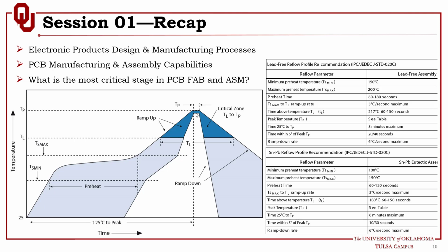So there is no specific or generic profile for all boards. No, there are several factors that govern the profile you are using for soldering. The factors are the maximum or peak temperature the electronic components can handle, and also the type of solder material you are using. So if you look at the soldering profile here, it can be divided into 4 areas or 4 stages.